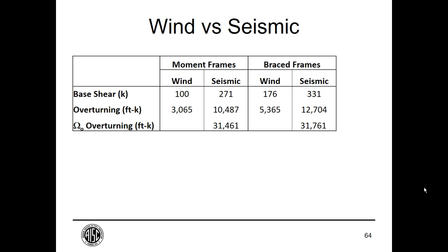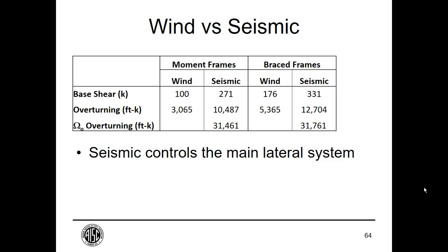So for this design, we definitely want to size everything for seismic loads and then verify that they meet the requirements for wind loads. It may not need to be a very detailed wind analysis. Maybe complete the wind loading analysis, but the level of comparison may not need to be more detailed than this for the primary lateral system.